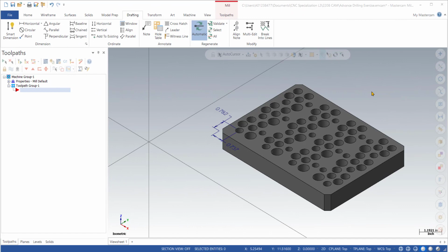So in this example, as you can see, the software origin and the part origin, or the part corner, are not aligned, right? It's somewhere else. In this case, generally what we do is we just translate the part to the software origin and then work from there.